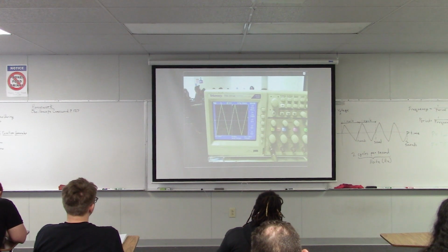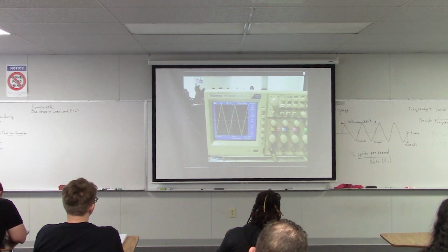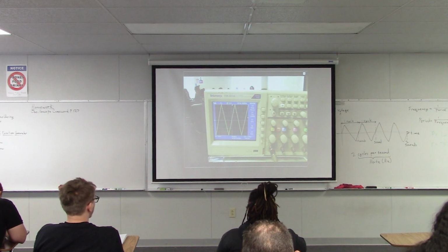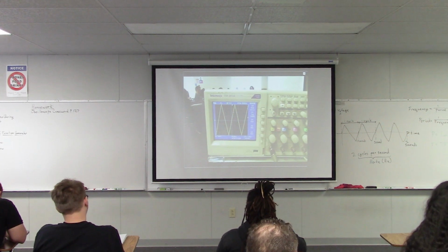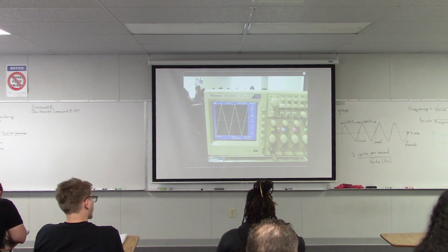That's a quarter of a millisecond. Yeah, so 4 of those gives you 1 millisecond for the period, and then the frequency is 1 over that, which is 1,000 hertz. Got it. Yeah, thank you. So that's how the controls work on the function generator and the oscilloscope. So any questions about that?